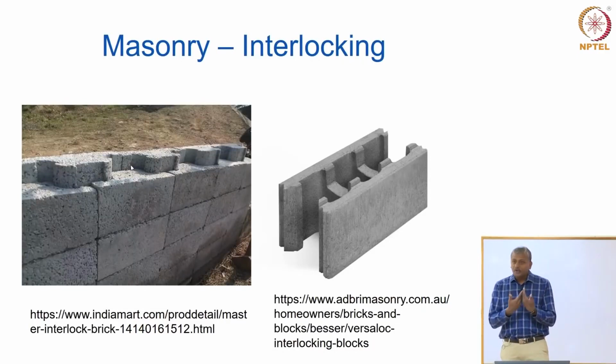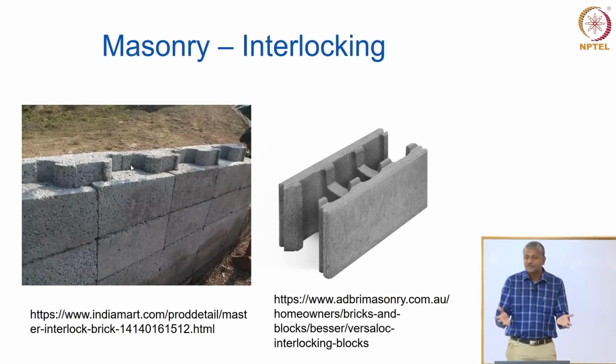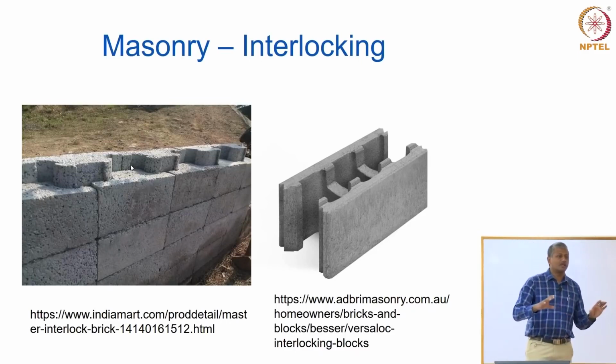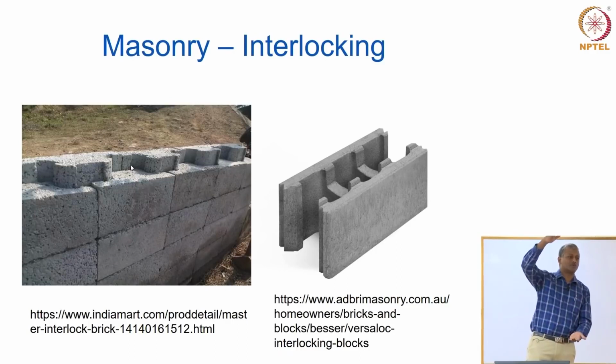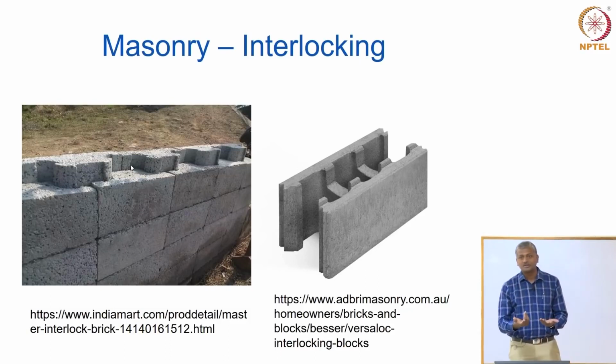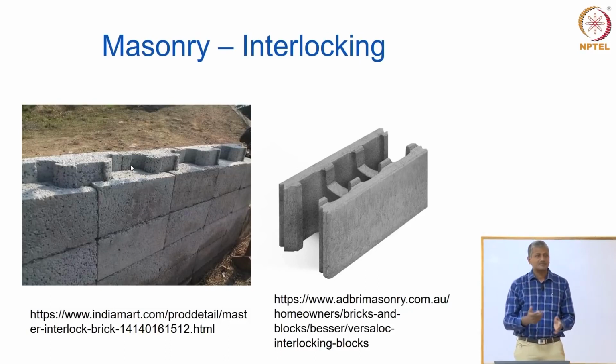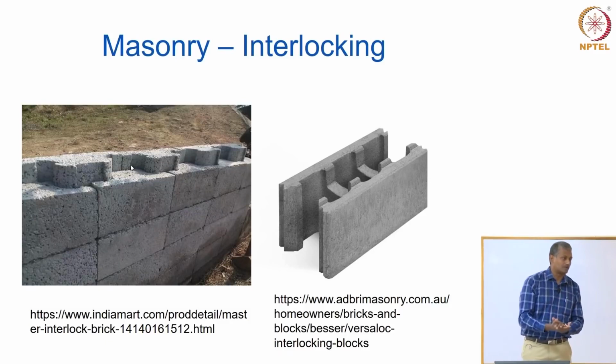Moving on from jointed masonry, you can actually get a lot more optimization with the speed of construction. Please remember, when you are doing a jointing process in a masonry block, you are placing one layer of masonry, then you have to actually place the cement mortar or lime mortar on top, which is the binding material, then put the next layer on. But you can't keep doing this entire process in a single day. You need to wait for the material to harden. Otherwise, the wall will become unstable and fall, right?